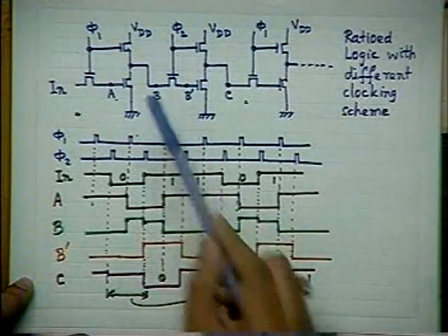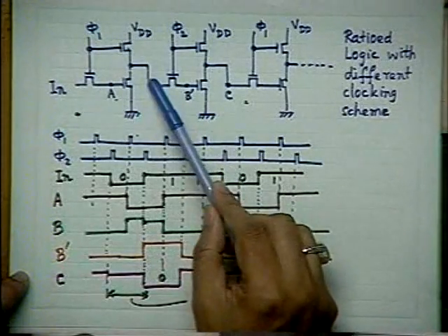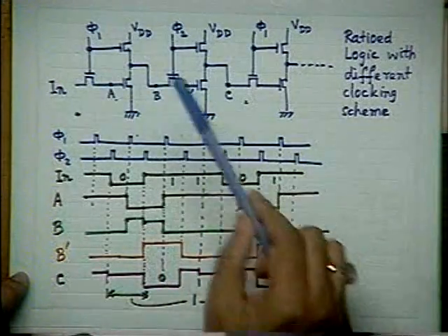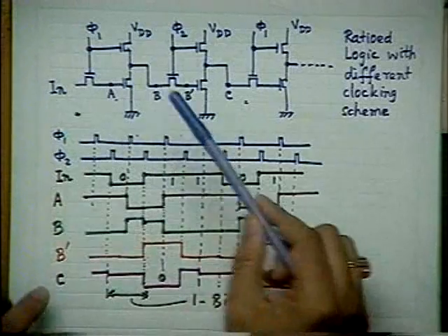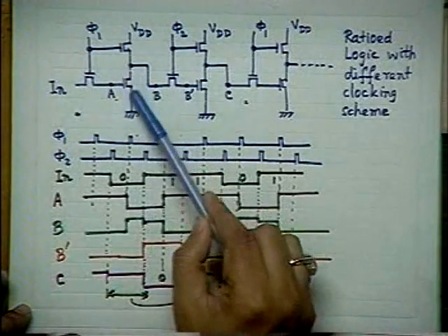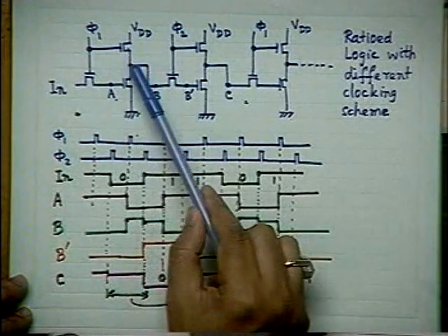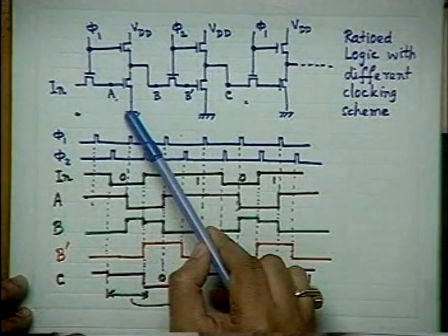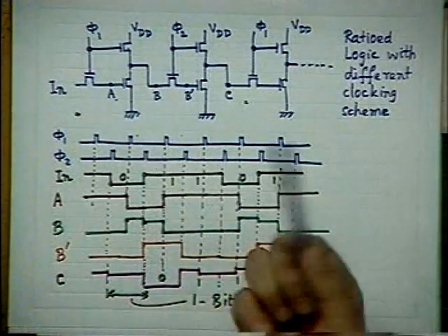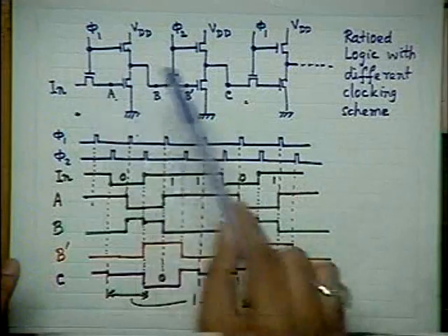And what about this? Here the most important capacitance is the capacitance when this transistor is off. I am speaking of when A is low, that means when this transistor is off. What is the capacitance at the node B with respect to ground? It is simply the junction capacitance of the drain substrate junction of this transistor. Am I correct? Now let us see the geometry.